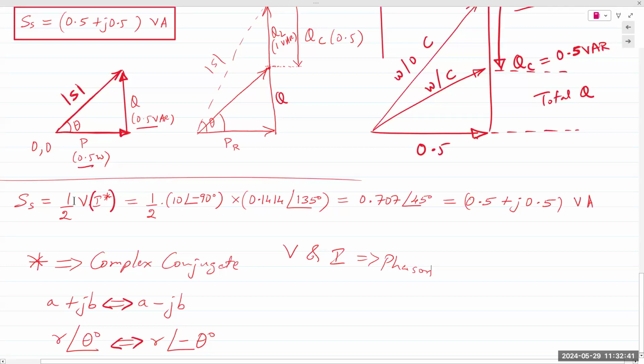But again, in all cases, you need either the voltage or the current. The source does not have any resistance or reactance, so you can't use the V squared over R or I squared times R equations. But for all components, you can use all three sets of equations.